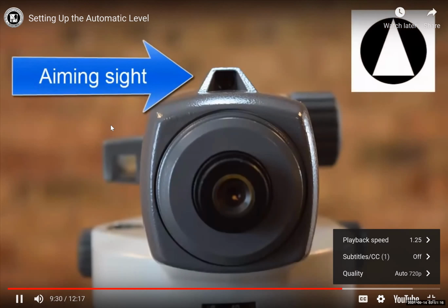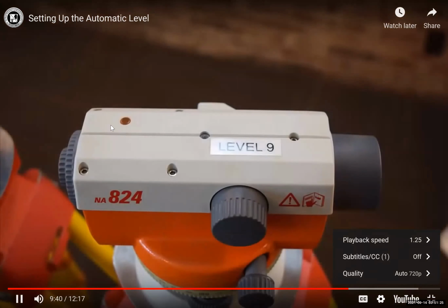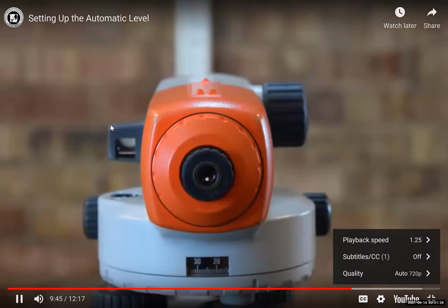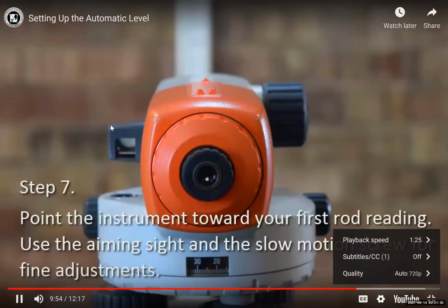When the white arrow roughly aligns with the level rod in the distance, you'll find the rod easily through the telescope. This instrument simply provides a groove along its top side to assist with rough aiming. This one has simple aiming sights like you would find on a rifle. Use your aiming sight along with your slow motion screw to find the rod easily.